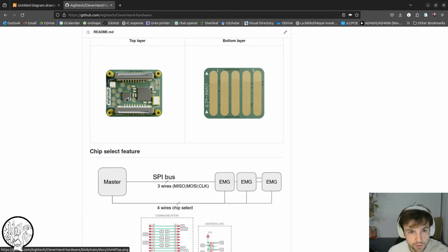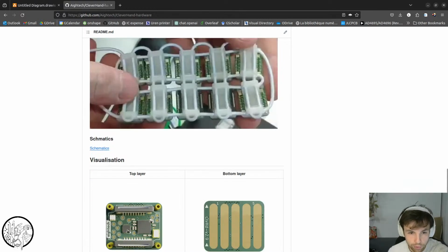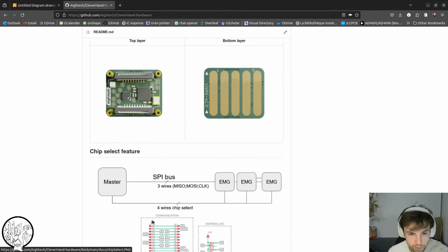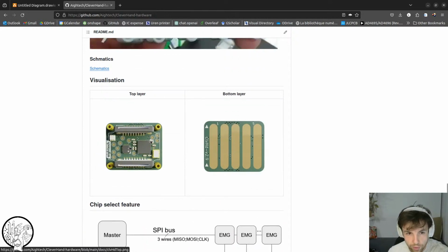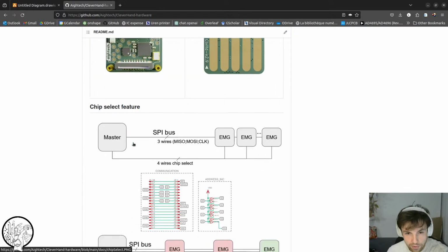Because I discovered this ARM microcontroller, which is super cheap. It's 50p, just this one, and you can program it, and you can use, I think, up to 16 GPIO all around, so this mechanism you could do directly just by software. This chip should be able to add 1 to the input pin, and propagate it with +1 to the output pin. So I tried that.